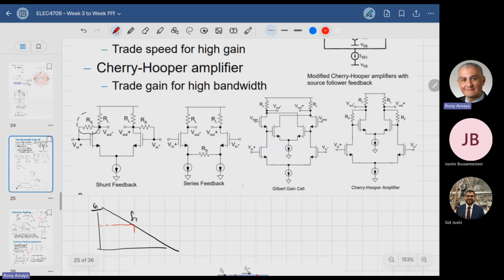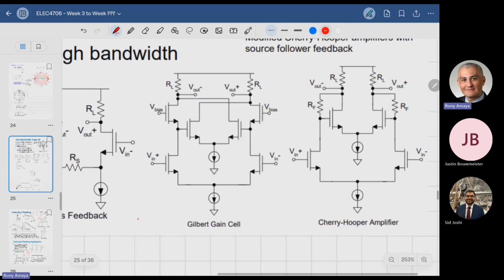So you can do it with a standard differential pair, or you can use it with a Gilbert cell. You guys know what a Gilbert cell is? Ever heard of it? Gilbert cells are effectively using something called a mixer, and it is effectively an equal differential pair with an upper quad, a switching quad, that allows us to multiply signals in time and basically translate them to frequency.